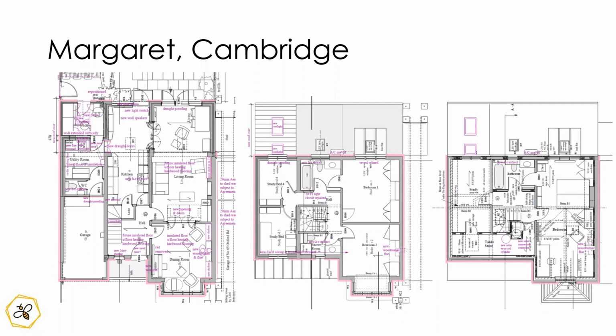Yes, or Margaret, if you fancied taking it on, you could try and work out your heat loss from your house, because I think you know your build-ups, don't you? Yes, I have looked at it and wondered for Cambridge what you would use for the lowest temperature. I think it's -1, or would it be colder? You mean design temperature? Yeah, design temperature. Well, again, I'd design for 0.